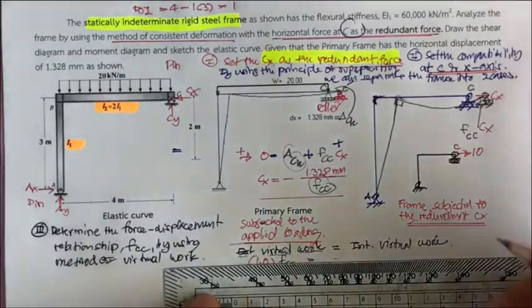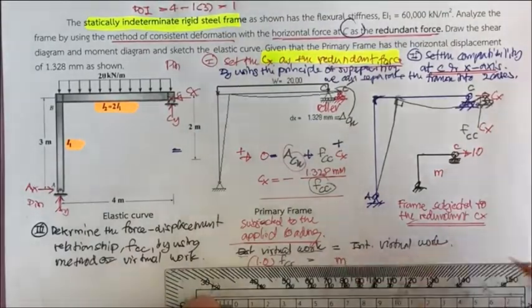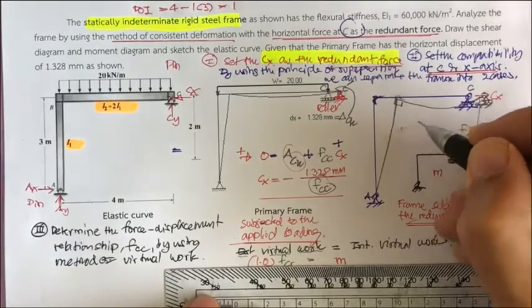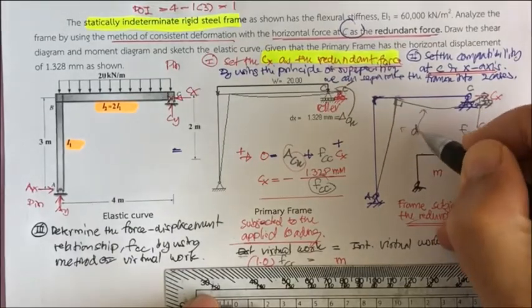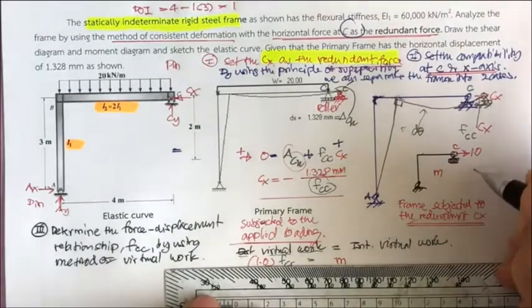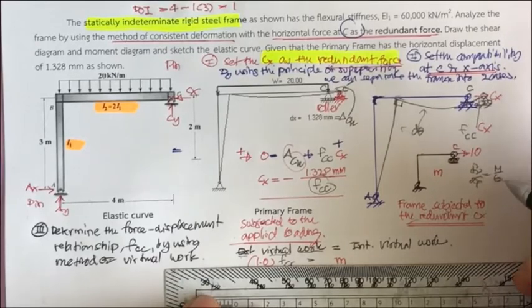This 1.0 is going to produce the moment M. So the moment M due to the 1.0, the moment M is going to multiply the deformation that occurs on this structure, which is d theta. And you know that d square v by dx square equals M over EI, and this is d of dv by dx.